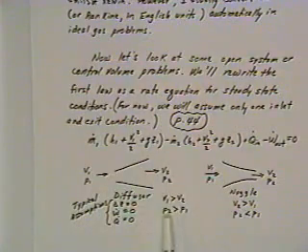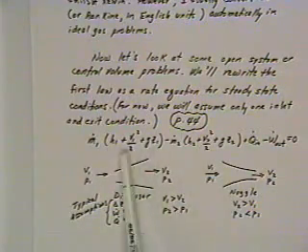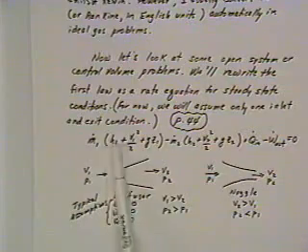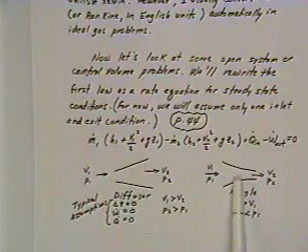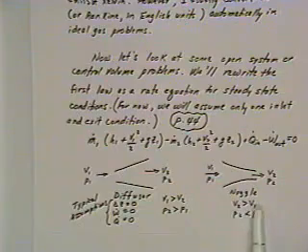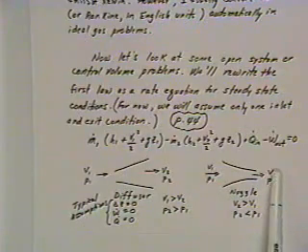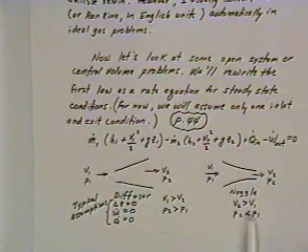So these are the equations that you're dealing with, and the terms that are generally significant are the kinetic energy terms and the enthalpy terms. For a nozzle, you've got just the opposite case: V2 is greater than V1, you're speeding up the fluid, and the pressure P2 is less than P1.